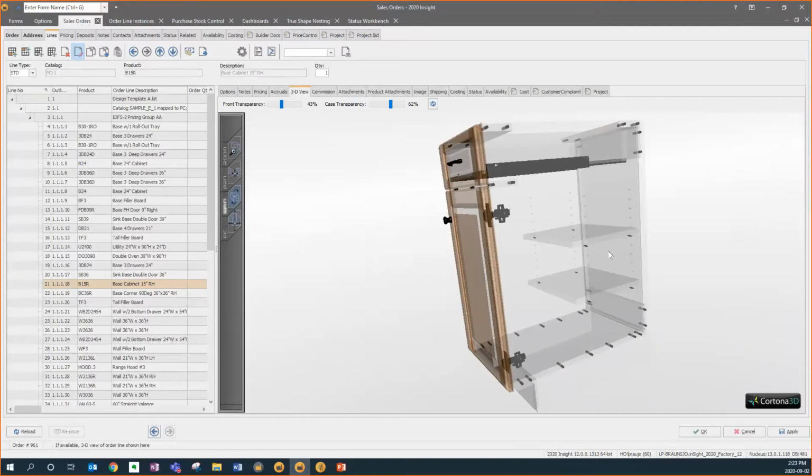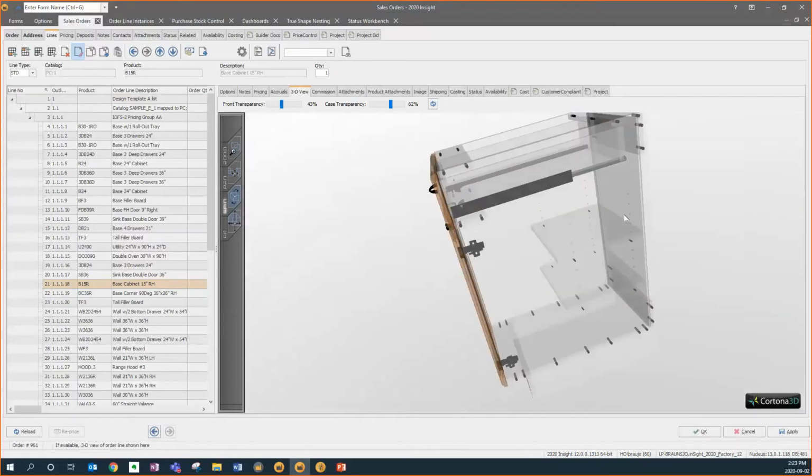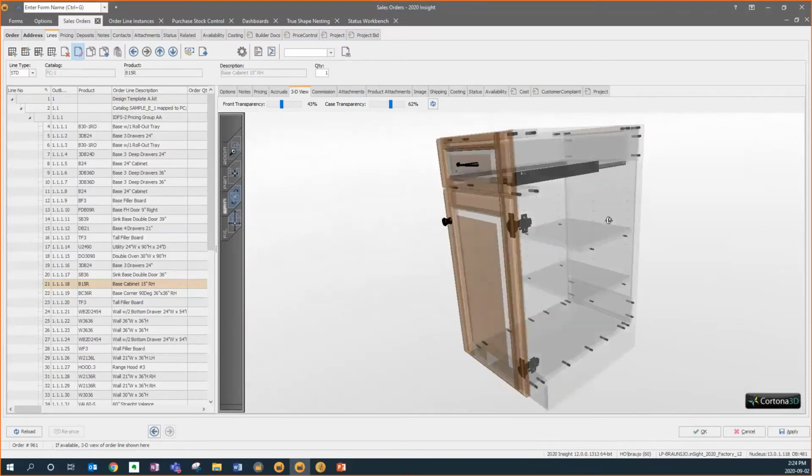So the system will then automatically generate a new CNC code for the left and right side panel. Same happens when I change dimensions and make the depth less, then automatically the system will find the next lower or smaller drawer glides and generates also new CNC programs for left and right side panel because of the new drilling patterns for the other drawer slides.